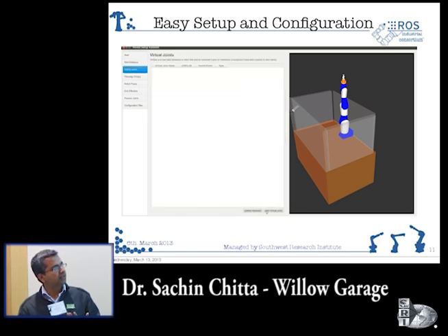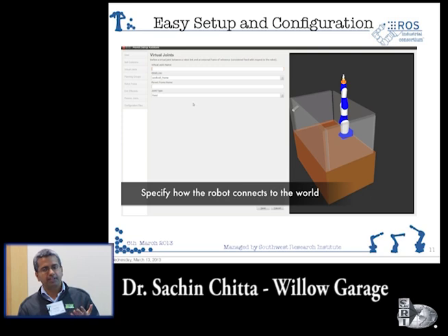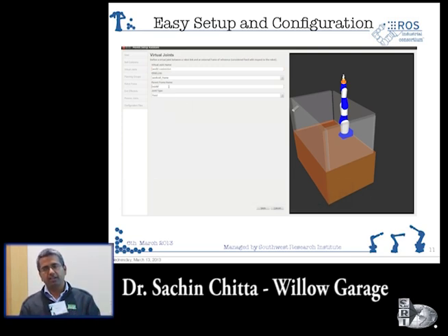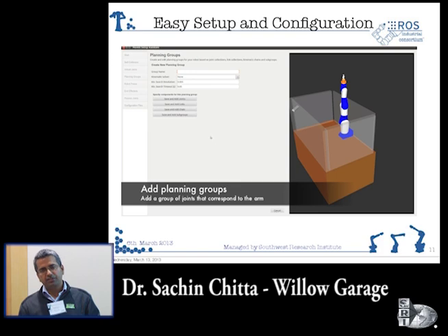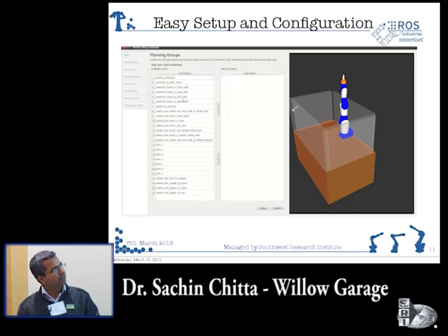And the tool that we use to do this is called the MoveIt Setup Assistant, and it basically works with the URDF, which is the base representation of a robot in ROS. So you always start with the URDF, and this actually comes straight out of the SwRI ROS package. We just picked up the URDF that SwRI has for these things and integrated it and set up MoveIt with it.